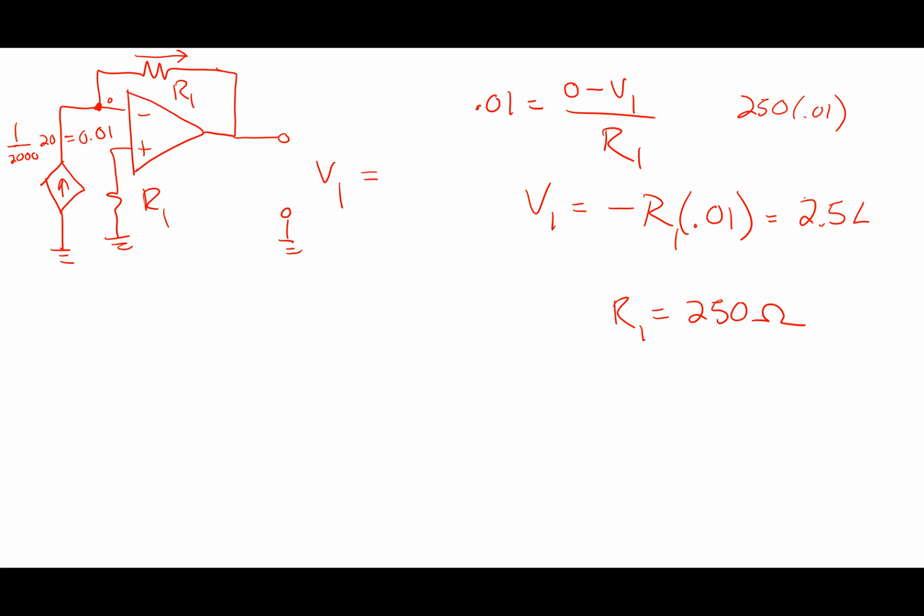Because the resistor is not going to be negative. When you solve this thing, you're not going to get a negative resistor. Yeah, 180. If somebody says, well, I need a negative 250 ohm resistor, right? That doesn't exist. A 250 ohm resistor does. The negative sign means that the voltage has a phase shift as it goes through the circuit, right? That's what the negative sign means. All right, so it would be that. Okay. Questions about that?